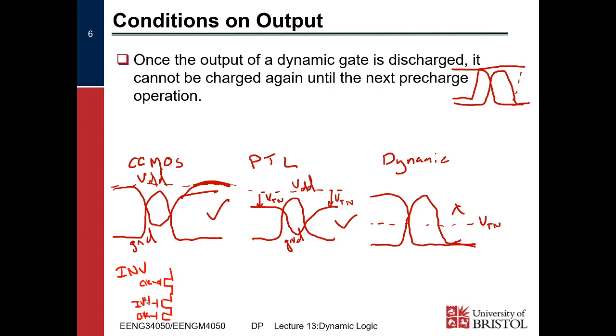I'm writing this very badly. Inverter. There's our output with its capacitance on it, right? Okay. So if we presume that our input is 1, what we'll see is that our clock is low, it'll go high, and then our output will discharge. This is obvious, right? And then we've got our propagation delay from the 50% points, right?